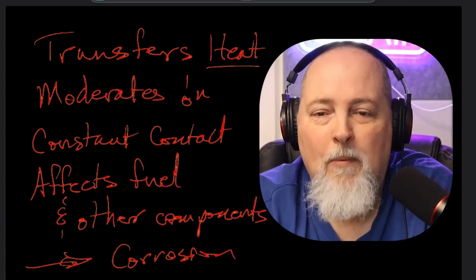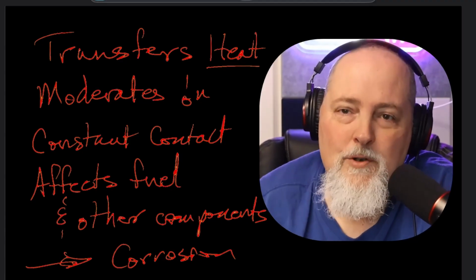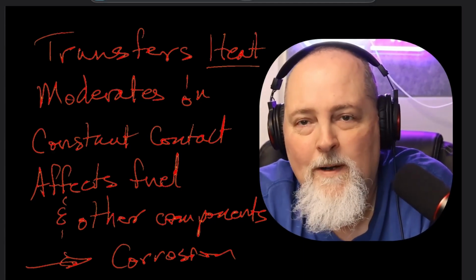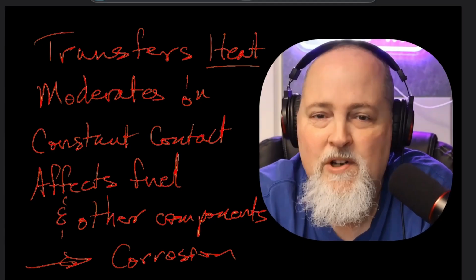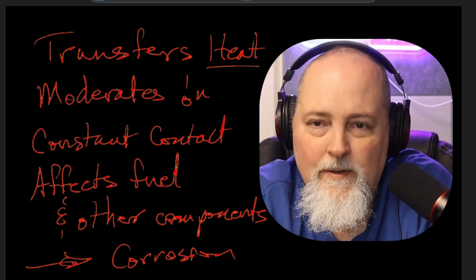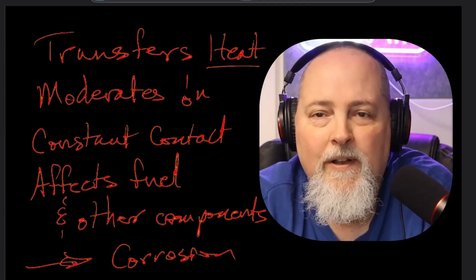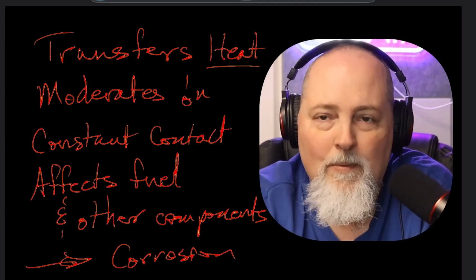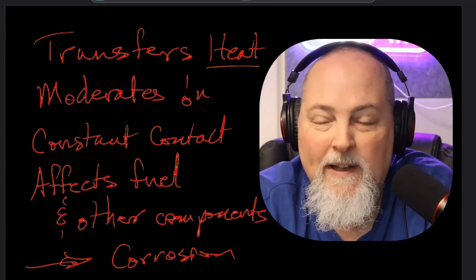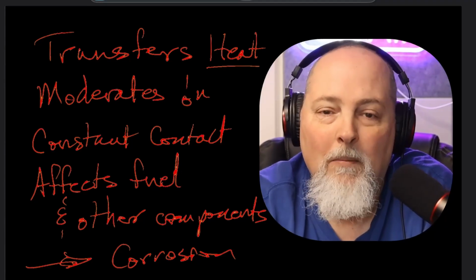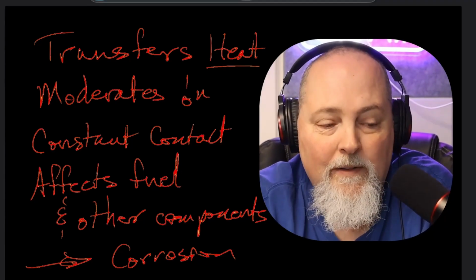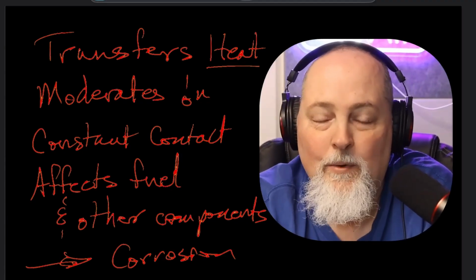So we have to keep all these things in control to minimize corrosion, because the main thing we're trying to protect here is the fuel. If any corrosion starts affecting the fuel cladding under the conditions in a reactor, the high temperature, high pressure, the corrosion can exacerbate really quickly and become a bigger problem, and eventually allow fission products to be released into the coolant, and it just goes down from there.